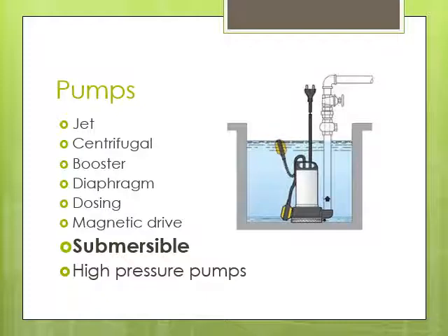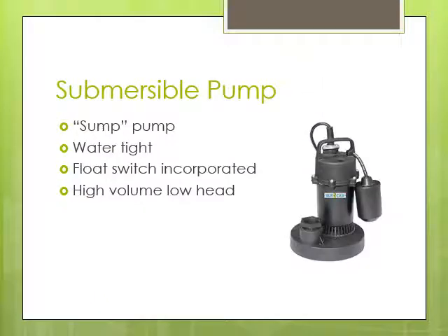We've all seen these submersible pumps. These are like your standard sump pump. Typically, they have a float switch that swings up when the water level gets high, and then that turns the pump on. When it swings back down again, the pump switch is off.